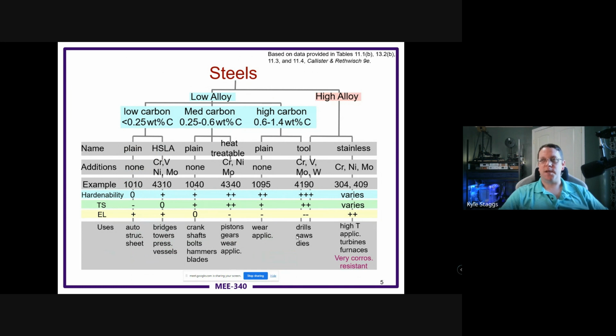So when you hear titanium cutting edge or something like that for tools, that's what they're talking about, a titanium carbide coated material that's probably a base tool steel like this. How professionally that was hardened probably depends on where it was manufactured and how, but that gives you the ability to have really, really good cutting bits, cutting drill bits and things of that nature.